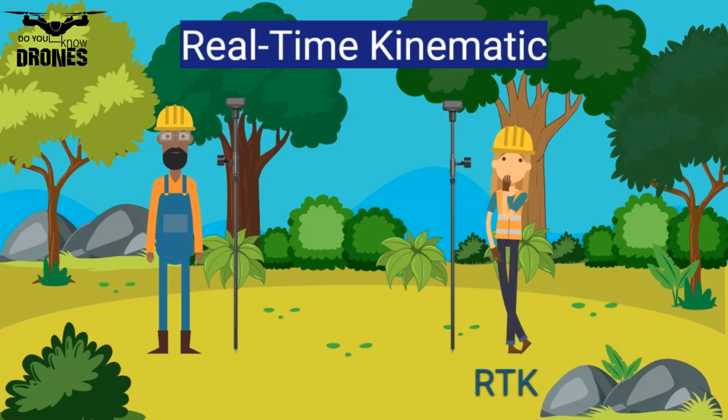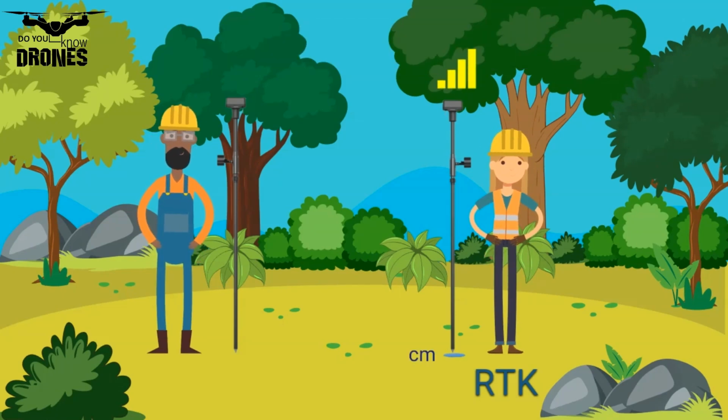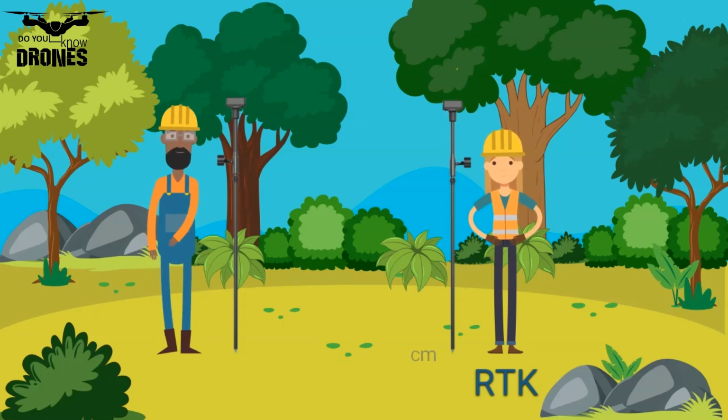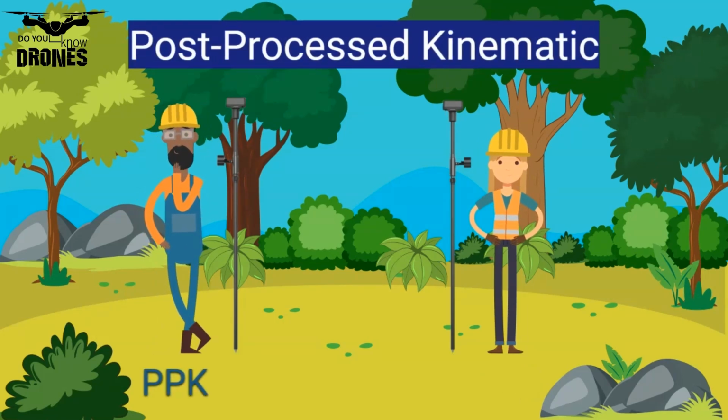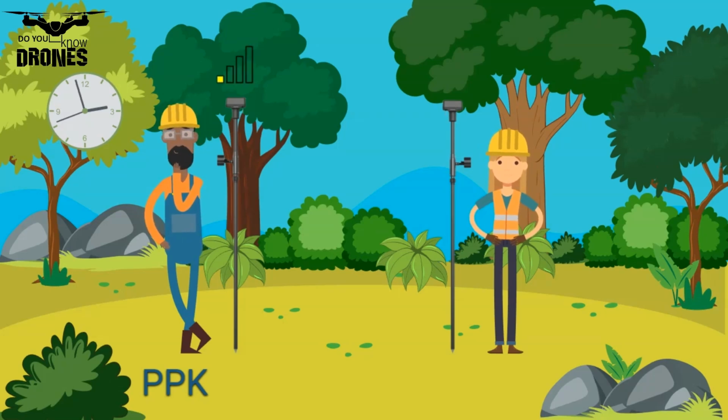RTK stands for Real-Time Kinematic. It's a technique that uses a base station and a rover to provide centimeter level accuracy in real time. With RTK, Jill can see her location on her receiver with high accuracy. PPK stands for Post-Process Kinematic. It uses the GPS data collected on site and processes it later in the office to achieve high accuracy. Jack can collect data in areas with poor signals and process it later when he has a stronger signal.